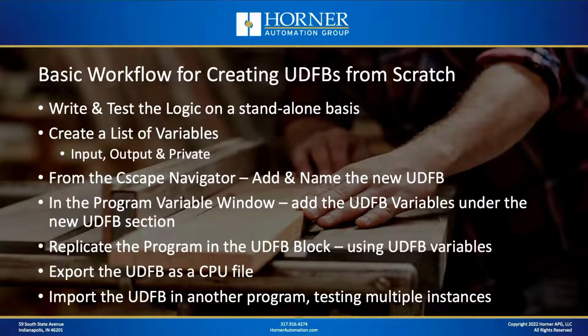Okay, once you've done that, you're going to create a list of variables. What were the inputs to the function blocks, or what are they going to be? What are the outputs from the function block? And then what are the lists of the variables that are used internally by the function block? That's all information you need to know as you're creating them.